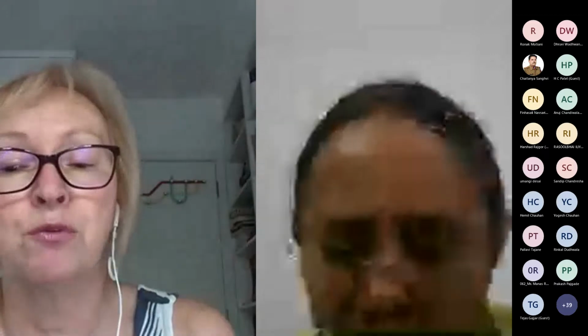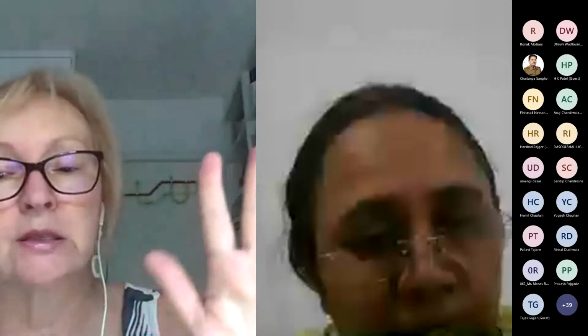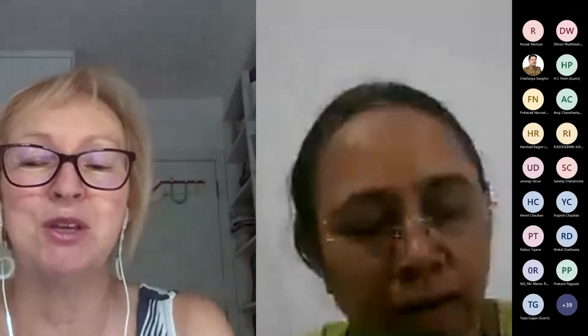In Mexico, for example, what they used as a repair technique, I have not talked about that. Now this whole course is about new construction. But in Mexico, they use techniques like what I just talked about with Ronak, with wire mesh reinforcing of the entire wall, and then plastering and grouting the cracks. So they have experience, obviously, in earthquakes with the damage of confined masonry buildings. So various techniques are available, but that is the mechanism.